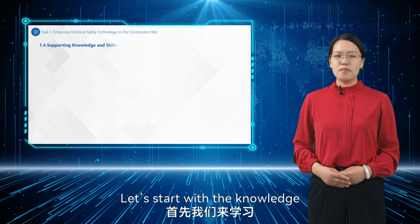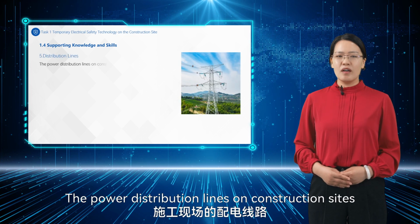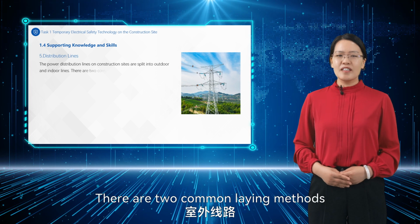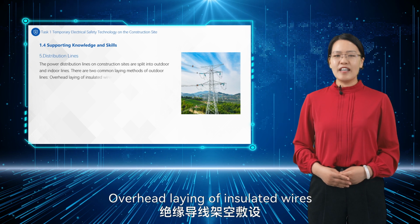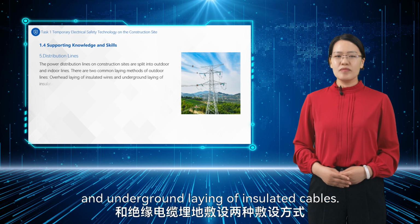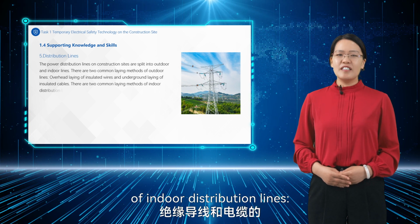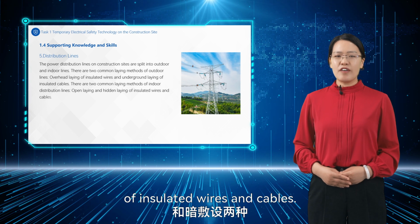Let's start with the knowledge about distribution lines. The power distribution lines on construction sites are split into outdoor and indoor lines. There are two common laying methods of outdoor lines: overhead laying of insulated wires and underground laying of insulated cables. There are two common laying methods of indoor distribution lines: open laying and hidden laying of insulated wires and cables.